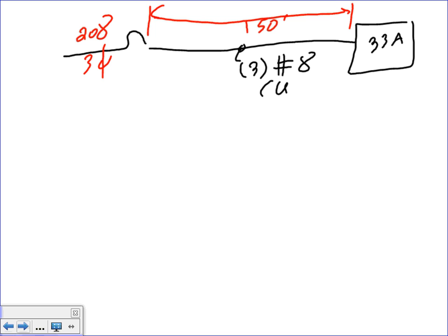I have a 3-phase load 150 feet away from a source, which is the panel, and I need to find the voltage drop. What's the voltage drop in this system? Everybody saw the criteria. Can you guys wake up one more time with me? When we do voltage drop, Spencer, if that was a motor, which full load amp would you use? The NEC code book or the nameplate?